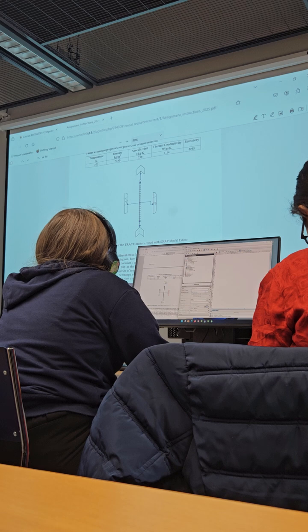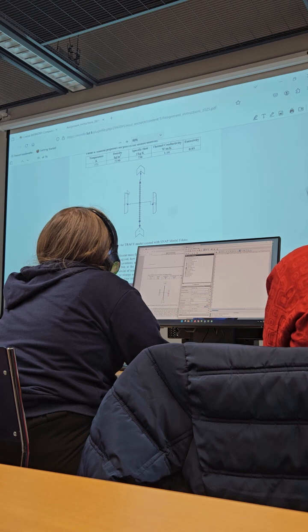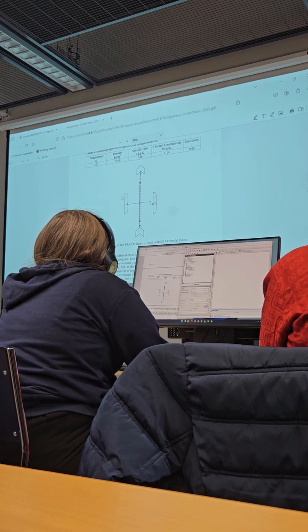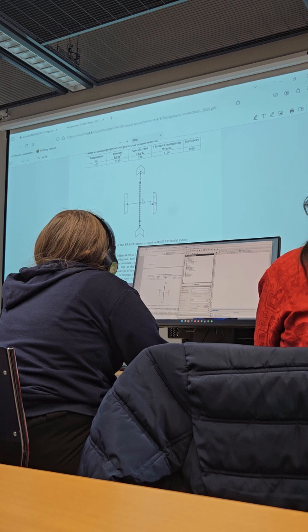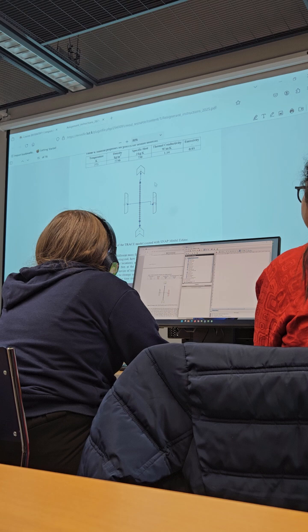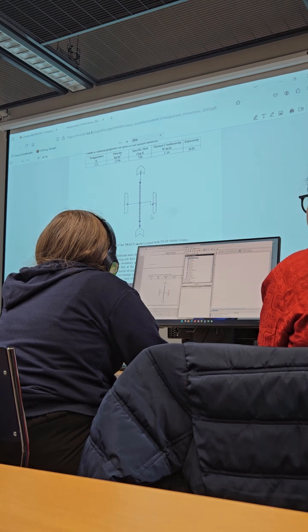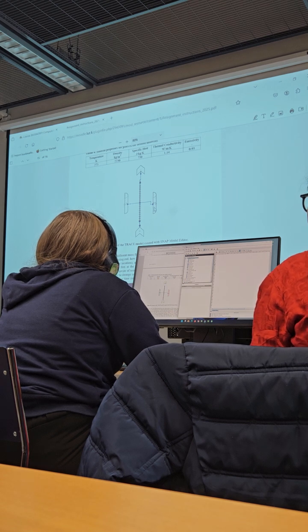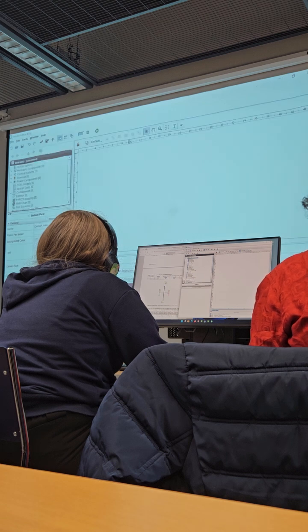So they have 2 boundary conditions, inner and outer. In the case of the fuel rod, the inner radius is equal to 0, so we don't have an inner boundary condition. We will only have the outer, which is connected to the internals of the glass tube. The outer heat structure will have both boundaries, inner and outer. The inner boundary will represent the surface between water and vapor and glass, and the outer boundary between glass and atmospheric air.